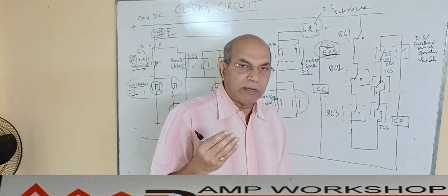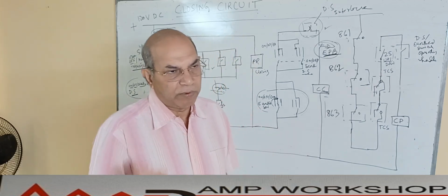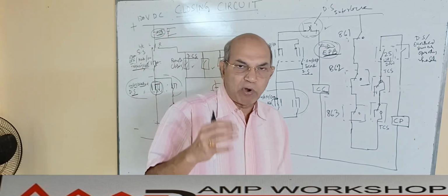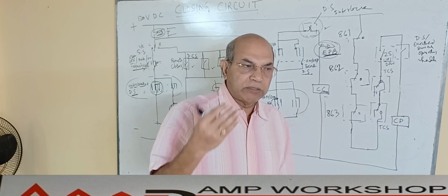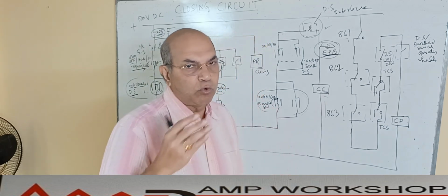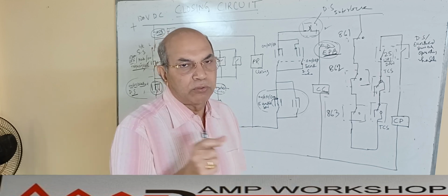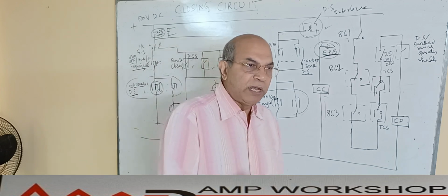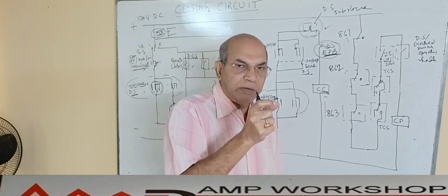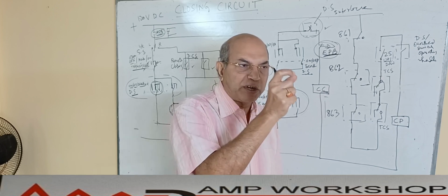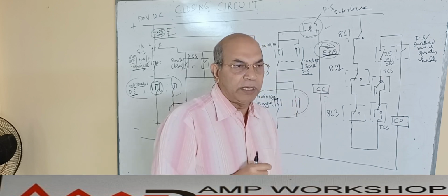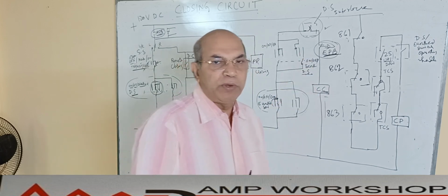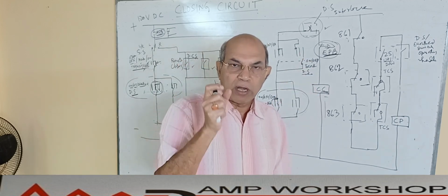So depending on how many protection functions there are and how important they are, the protection functions can be grouped into 1, 2 or 3 groups. Each group is activated once that group's protection functions operate in the numerical relay. The output of the numerical relay then activates one lockout relay.